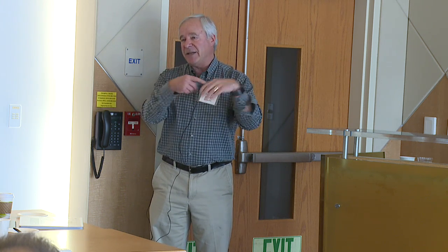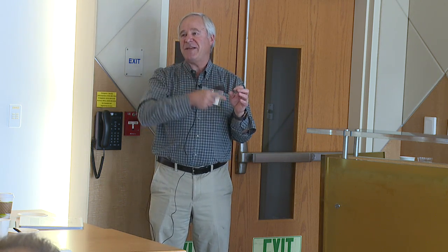When we tested this one, all the VAV box manufacturers said, our flow cross, when it gets down to really low, it doesn't amplify anymore. It just falls apart. We said, oh, really? Okay, well, let's just test it. So we tested them. Every single one of them went all the way to zero with the same amplification factor as it had at high velocity. Perfectly linear, all the way to zero. And all of them said, geez, I didn't know that. They didn't know because they never tried it, right? Because somebody told them a long time ago it wouldn't work, and they believed him.